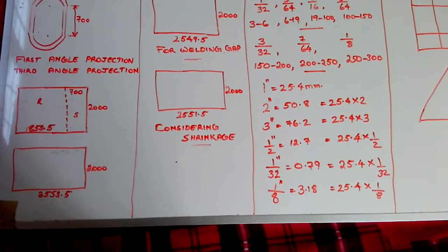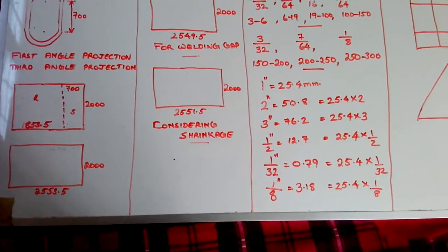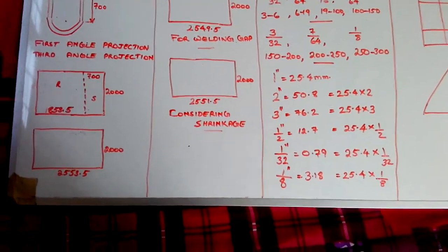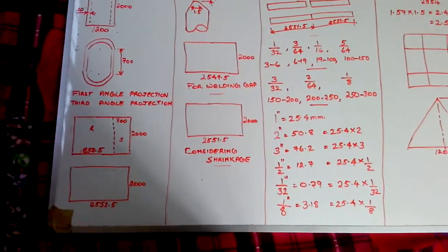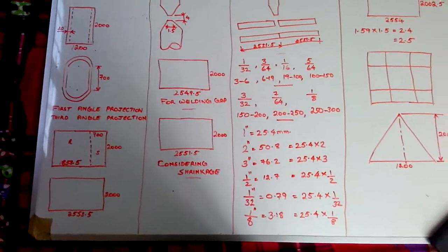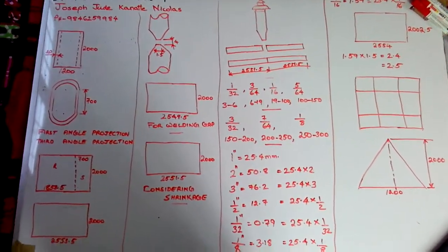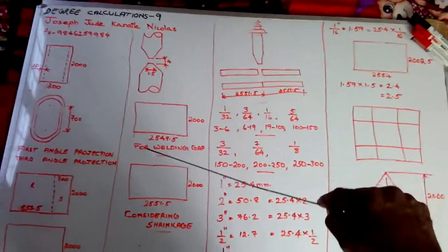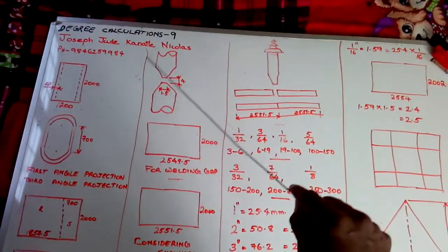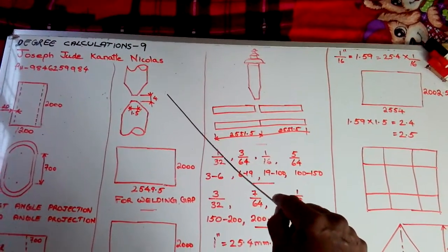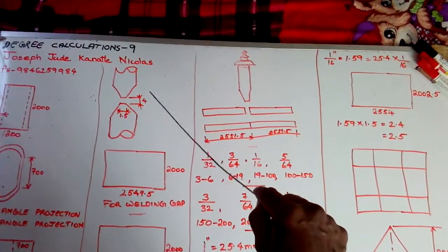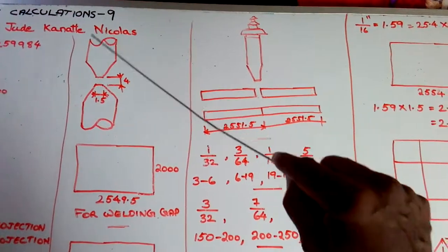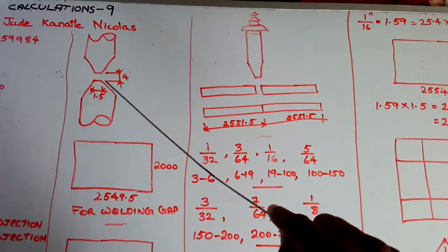It is a good habit of a fabricator, of a structural supervisor or fabrication engineer, that before starting these works, we take proper estimation and calculate the proper procedure, and then do it. It means before taking this measurement, we have to decrease the length for getting the 4 mm gap. In this plate, we have to decrease 2 mm. In this plate also, we have to decrease 2 mm.